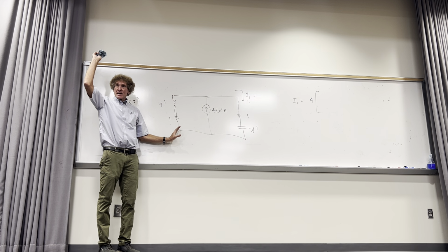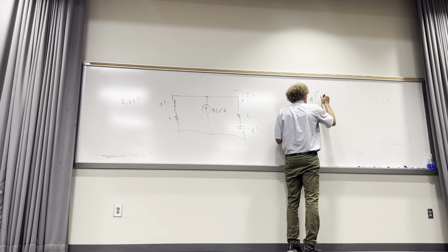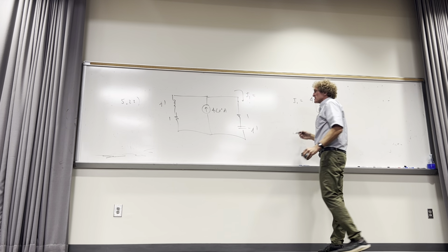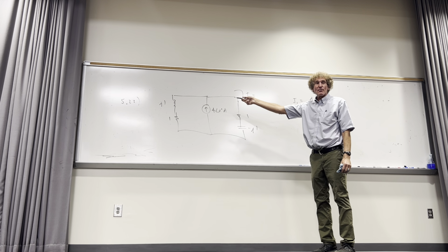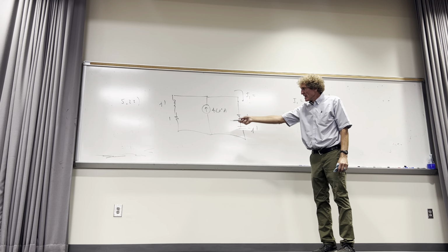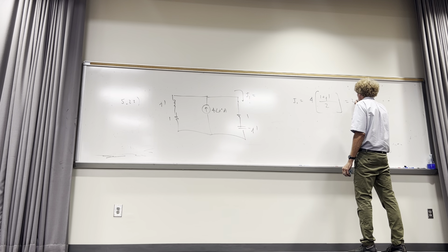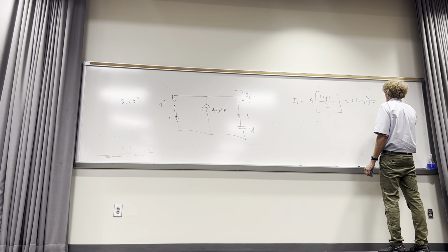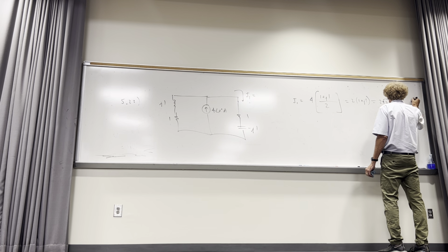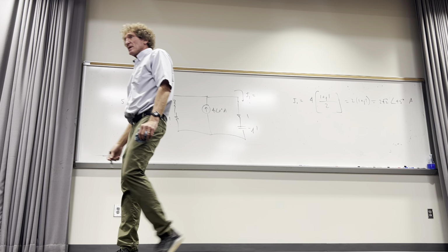How many understand that? Okay, opposite impedance is going to be 1 plus J1 over the sum of that plus that. What is the sum of that plus that? Kind of nice. Minus J1 plus J1 goes to 0, right? And I got 1 and 1 is 2. So I really have what? 2 times 1 plus J1. Or you can render this if you want in polar as 2 square root of 2 at an angle of 45 degrees amps. Now just take a look and make sure there's nothing that confuses you. Y'all with me on this class?